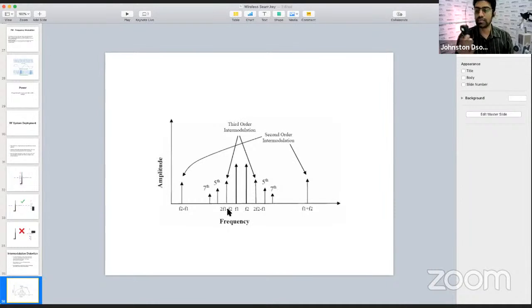Anytime you're setting up a new system, say you go to a venue or a new set and you're setting up a new RF system, you first make sure all the transmitters are turned off, after you've done your wiring and checked all the power supply everywhere. This here is the transmitter, it is turned off, there's no power. You take one of your receivers, and you can do a scan.